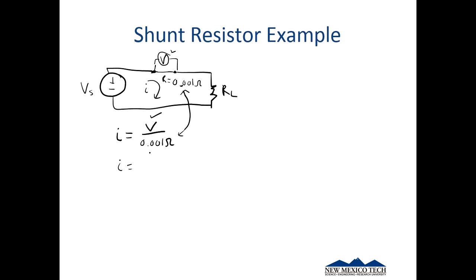Because suppose you accidentally got 1 ohm's worth of dust in there, that would lower your total current. So the way we did it was we had the shunt resistor in there, we knew its resistance value, and then we measured the voltage across it, and so we knew how much current we were running. There's also another way to do it, but for metering, this is a lot easier. We can measure voltage and it works out.